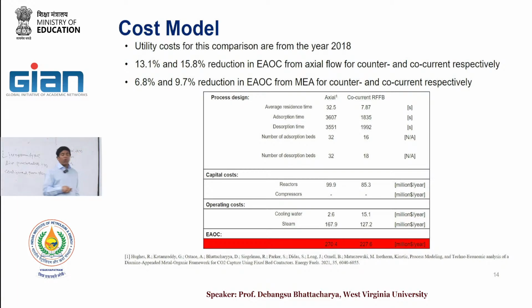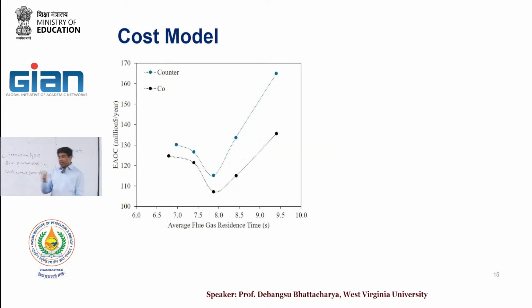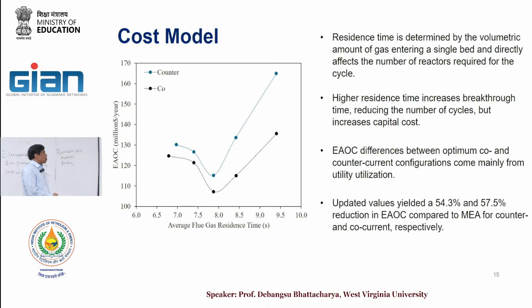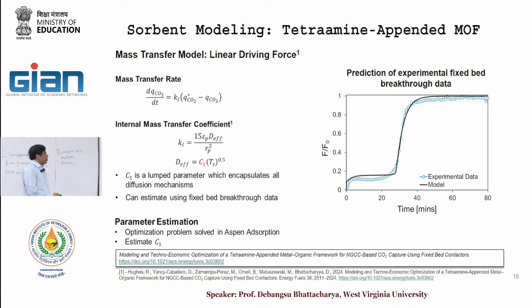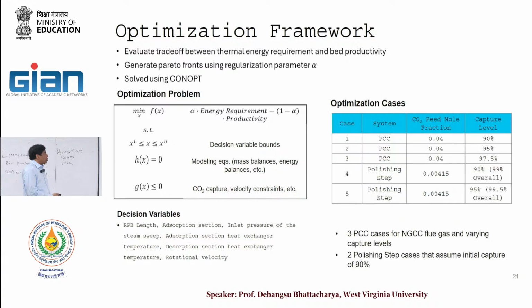Yeah, you see that adsorption time and the desorption time for each one of them. So if you are saying I have got these 360 and it's about 1 hour that I'm keeping, then after 1 hour I have to desorb. So you are heating it up every 1 hour. This is the biggest issue. Recovering that heat is very difficult because it's a dynamic process, right?